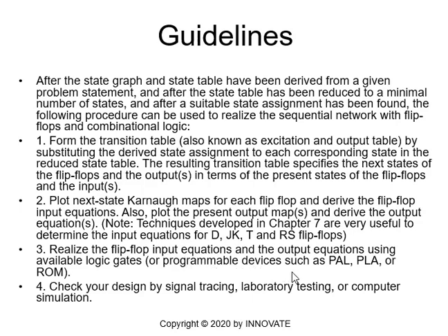Step number 3, realize the flip-flop input equations and the output equations using available logic gates for programmable devices such as PAL, PLA, or RAM. Step number 4, check your design by signal tracing, laboratory testing, or computer simulation. And this really will be the end of the design, the complete design of a synchronous sequential network. And this would be mainly the goal of this lecture and the goal of this chapter and mainly the goal of this course.